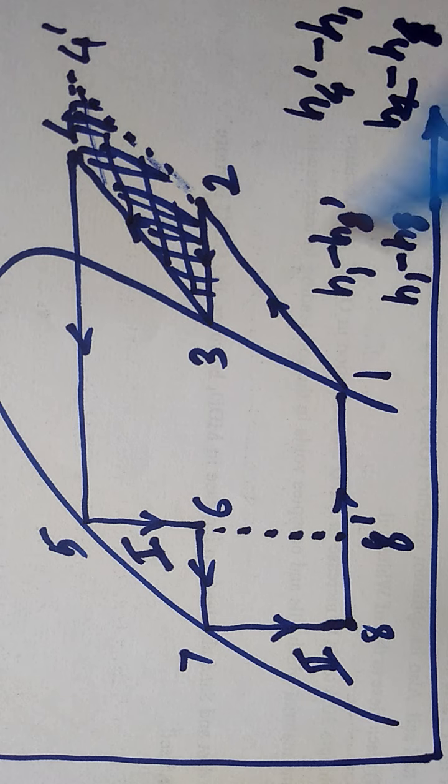And these are the reasons that instead of following a simple refrigeration cycle with single stage compression, we should follow multi-stage compression and a multi-evaporator system for more coefficient of performance. So this is the necessity of multi-stage compression instead of single stage compression.